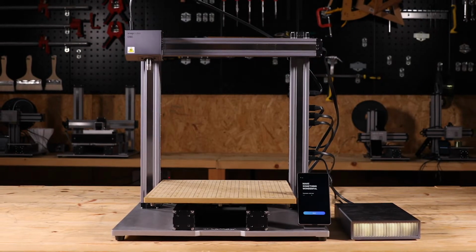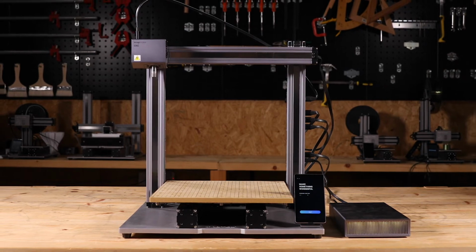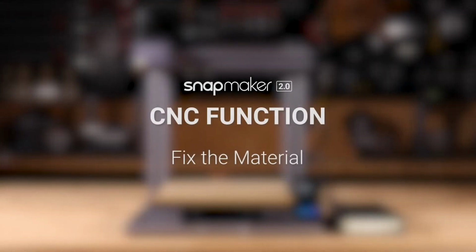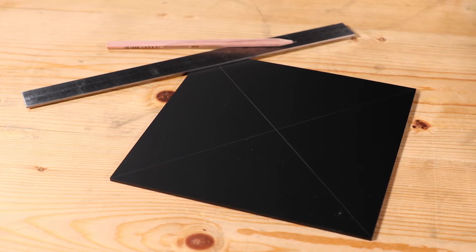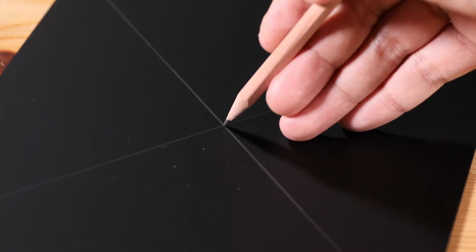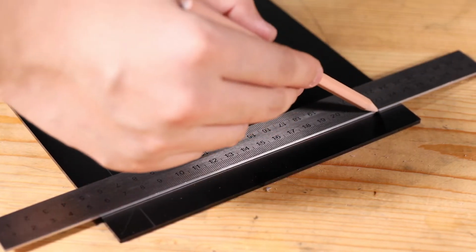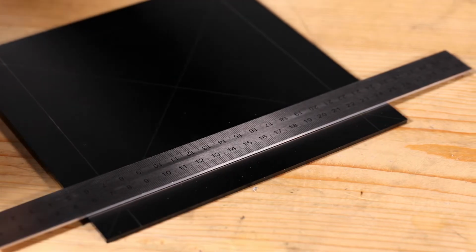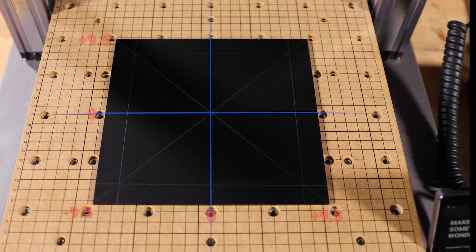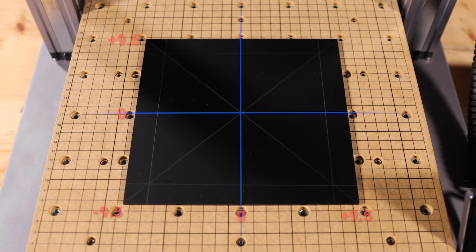In case of collision or carving failure, beginners are advised to set the carving area around the center of the material. Steps are as follows. First, find the center of the material and mark it with a pencil. Second, mark the carving area. Estimate the largest possible carving area according to the model size and mark it on the material. Or fix the material directly with the help of the auxiliary lines on the platform.